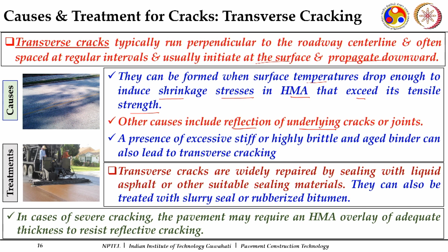These cracks get moved up to the surface also. We can call them reflection cracks in that particular case. The presence of excessive stiff or highly brittle and aged binder, because if that is so, they are prone to low temperature cracking specifically.